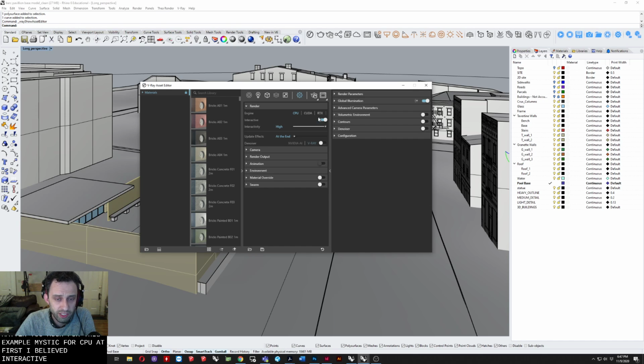First up, we have interactive. And all this does is that while you're rendering, as you make changes in your model, changes to the textures and lighting, all that kind of stuff, the render is constantly updating. So it's not rendering a static image, it's constantly updating with whatever changes you make. This is really useful when first setting up your rendering, testing lighting, creating those materials and everything, because you get real-time feedback as to what you are looking at. You can toggle it off, and it will open up another setting here, which is progressive, which is essentially the same rendering process, but isn't interactive. And you can toggle that off to go to what is the sort of standard renderer. And this is what you'll want to do when you want to make your final version of a rendering.